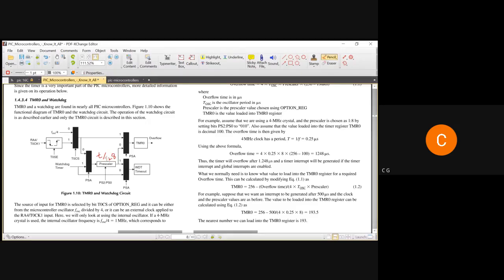128. So after whatever is this divided by, so 1 upon 128. If I design it like this, that much delay will be added by the prescaler. So after say 128 clock pulses, it will generate one pulse. That pulse is acting like a 1, and this is also some sort of a 1 here. So when this 1 and 1 match, then this gate will generate clock pulse 1.